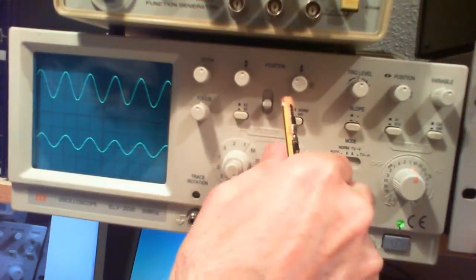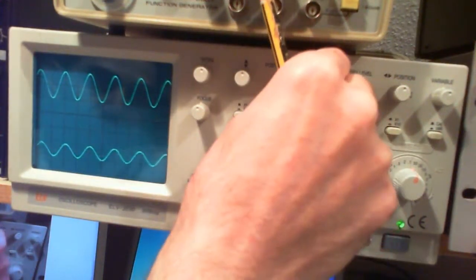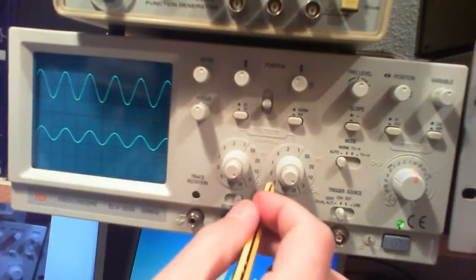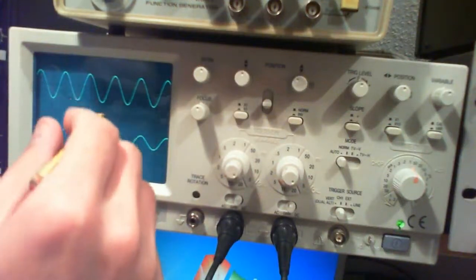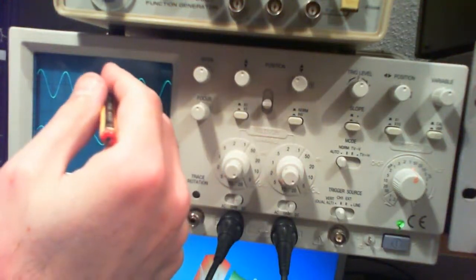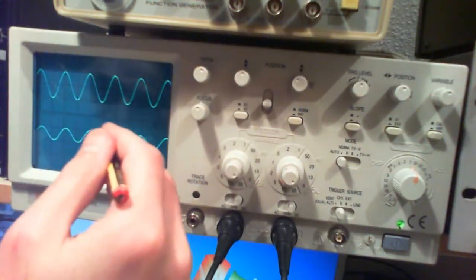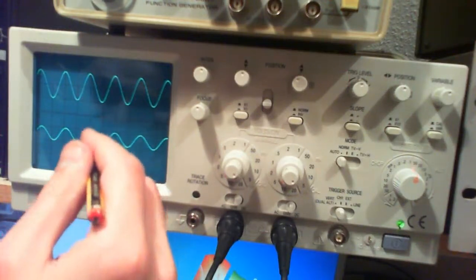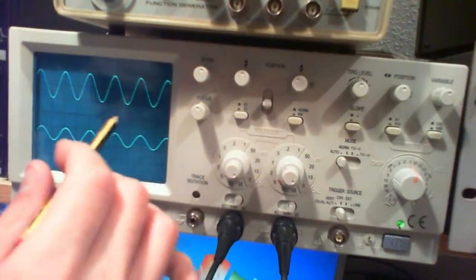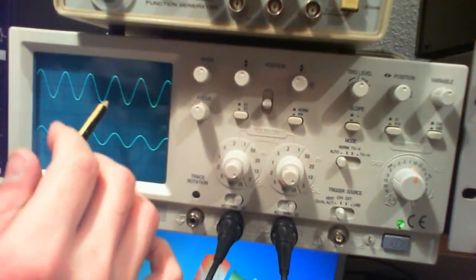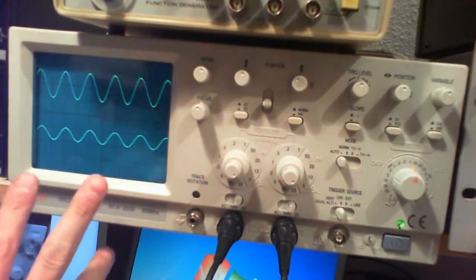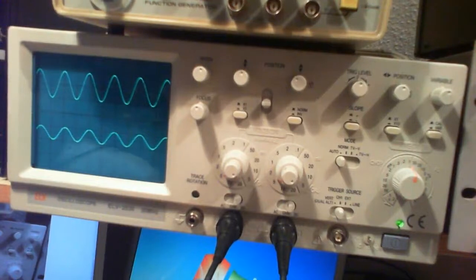the output itself, as you can see, is basically one vertical unit, which is 5 volts, so 5 volts peak to peak, but here your input is 10 volts peak to peak. So that means that your input is 10 volts peak to peak AC, and your output has become 5 volts peak to peak AC. Then on your input you have a 10 volts DC offset, and on your output you have a 5 volts DC offset. So that's basically what happens to your signal through this circuit.